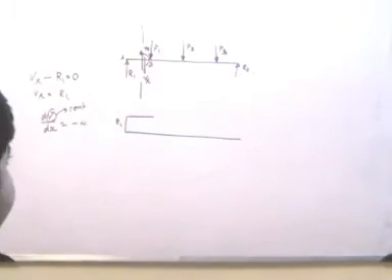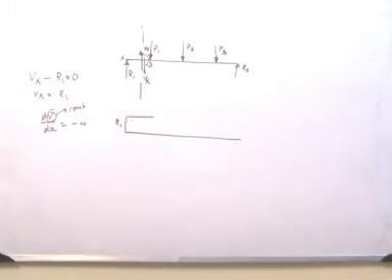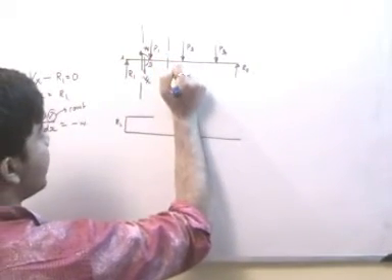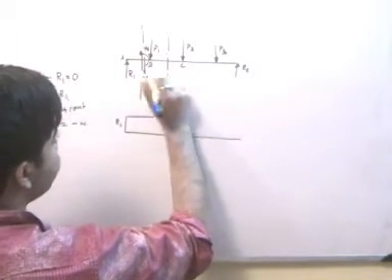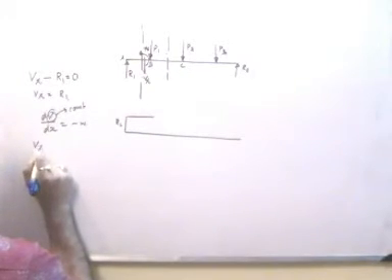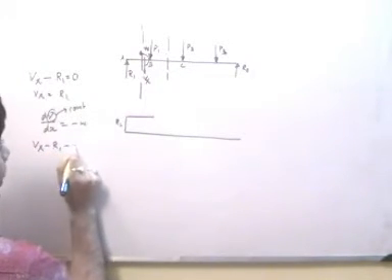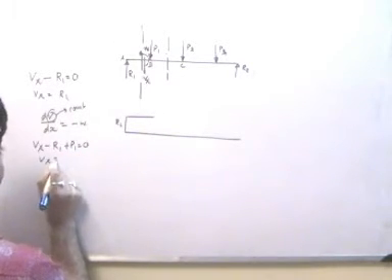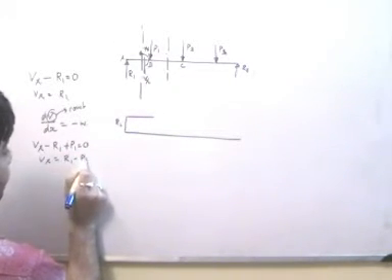At B there is a transverse concentrated load in the form of P1. Therefore in the region defined by BC, I will have Vx minus R1 plus P1 equal to 0, so Vx is equal to R1 minus P1.